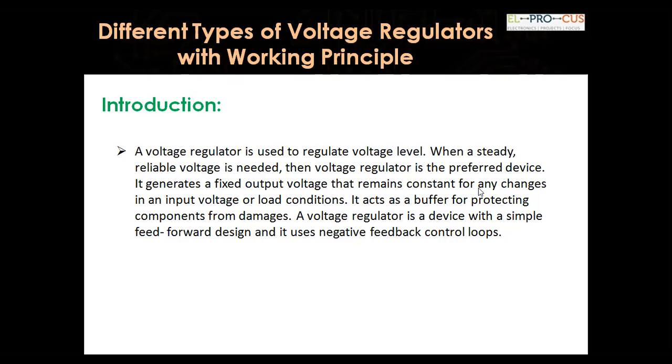When we are using the voltage regulator, we use some parameters with respect to it, like line regulation, load regulation, and temperature stability. It means that irrespective of changes in input voltage, changes in load condition, or changes in temperature, we will get a constant output voltage.